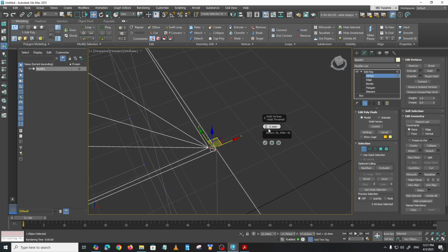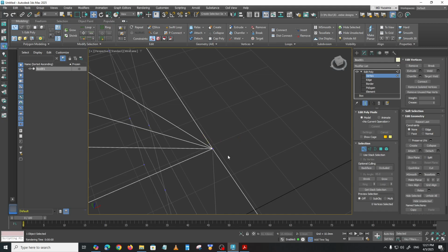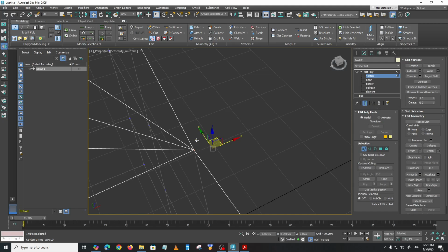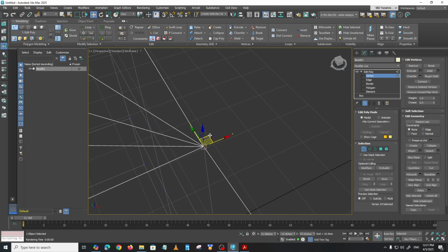It's because the threshold here is very little, 0.1 mm, which means the search distance probably isn't far enough for these two to find each other. So you need to increase this a bit. Maybe if I put 1 mm, this distance will reach each other. If I click OK, the green button, see it merged together. If I click one and move it, it is actually together now.